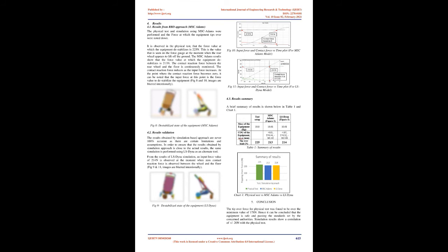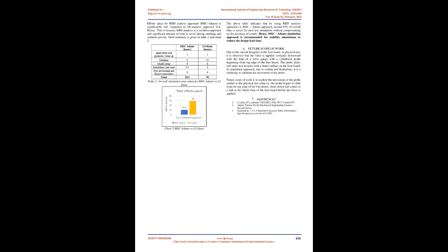The contact reaction force between the rear wheel and the floor is continuously monitored. The contact reaction force reduces as the input force increases. At the point where the contact reaction force becomes zero, it can be noted that the input force at this point is the force value to destabilize the equipment, Fig. 8 and 10, images are blurred intentionally.